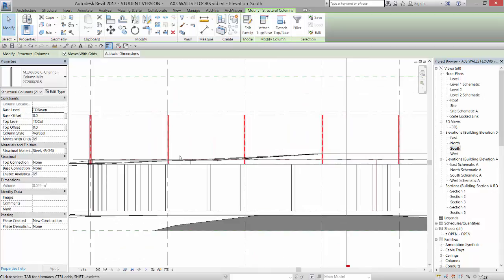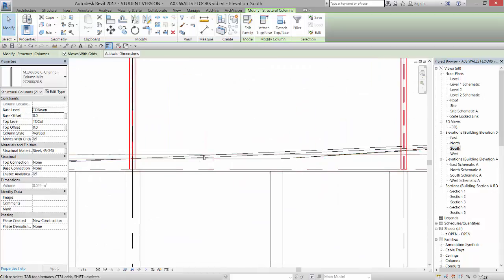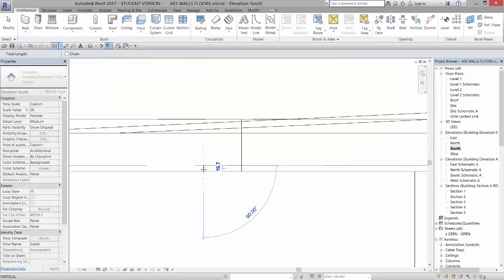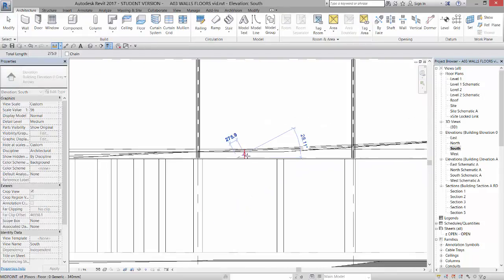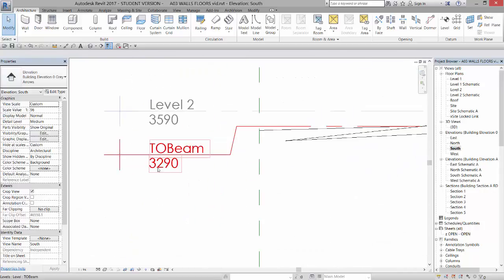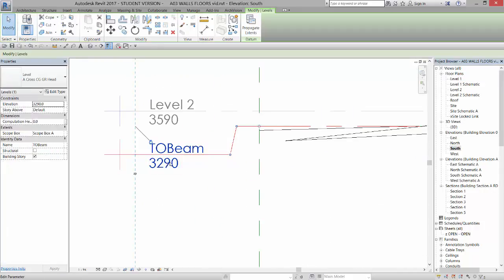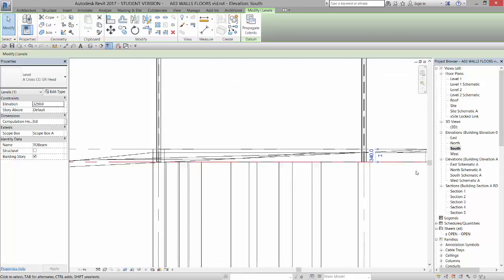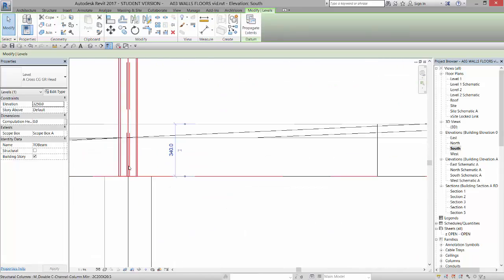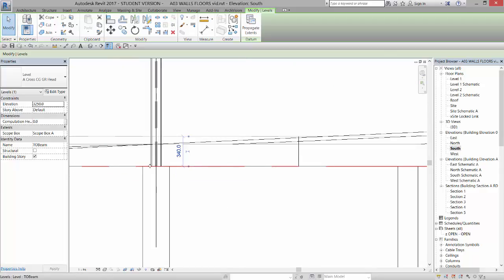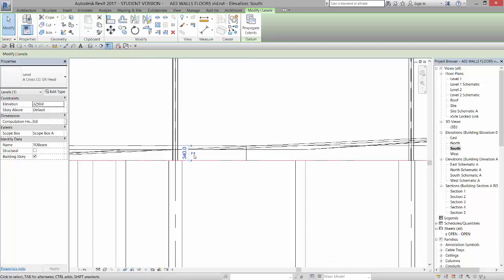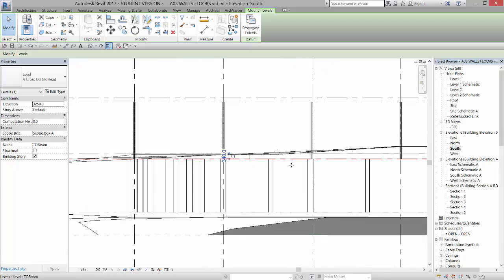which I think actually the top of beam is a little high. It should be coincident with the bottom of that floor. So I'm just going to do a little distance here, and that's a 40 distance. So this needs to be 40 units lower. So I'm just going to left click on this and subtract 40 from 90, which will be 50, and hit enter, and that will bring that down coincident with the floor, and these will follow. The next thing we're going to do is put the beams underneath these so they can be resting on something.